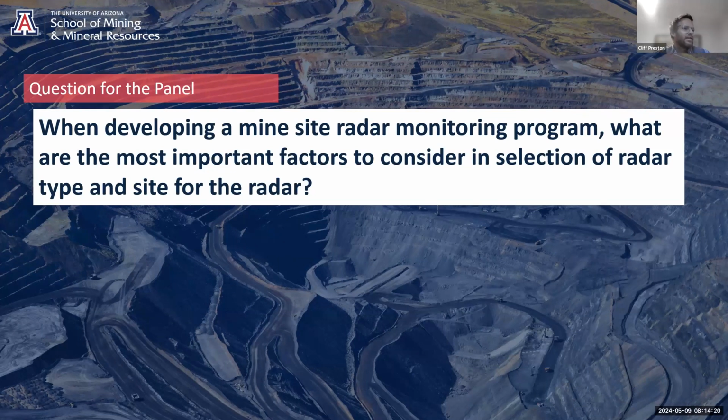Yeah, sure. I agree with everything Albert said, and there are just a lot of factors to consider when you're looking at a slope and what the goal of the monitoring campaign is. Line of sight, the visibility: can you see that area? How close or far do you want to be? What are all the areas you want to cover? Budget could play into that. Also, where are operations, so you don't have to put it somewhere that you're going to have to move it often? There are just many things to consider.